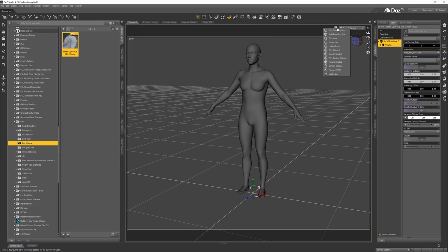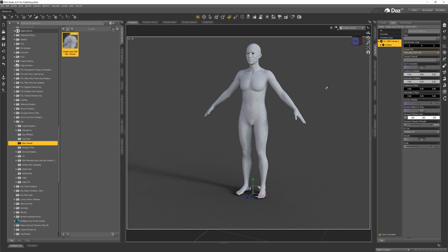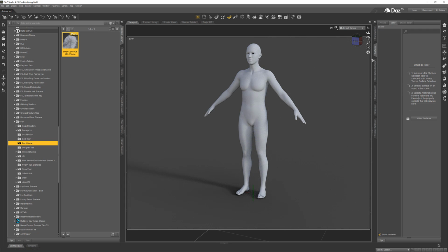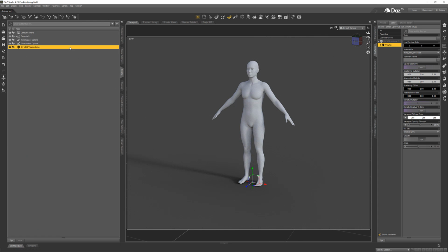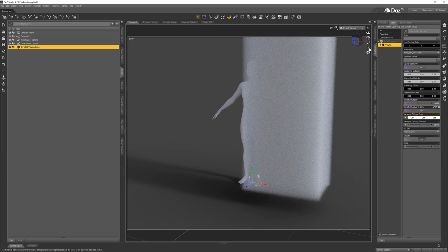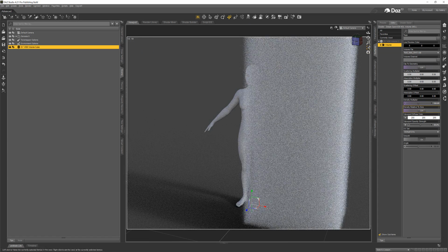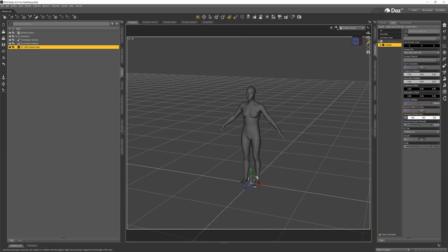And now I'm going to go to this drop down at the top right of my screen and choose NVIDIA iRay for draw style. And we don't see anything because I forgot to turn off clip to geometry. That's very important over here on the right. And we still don't see anything. So I'm also going to set my density multiplier to 150. There's my cube.